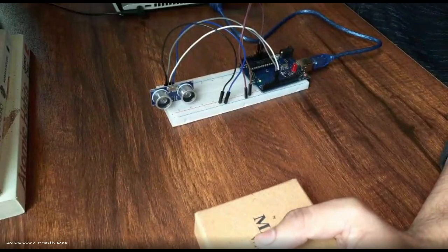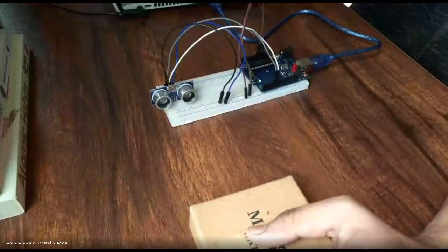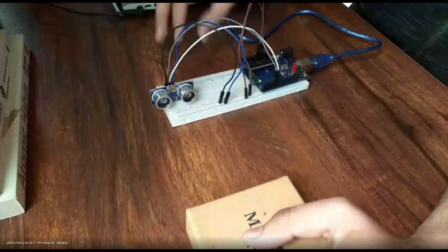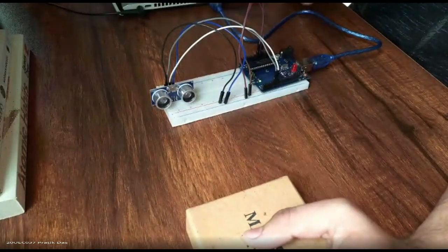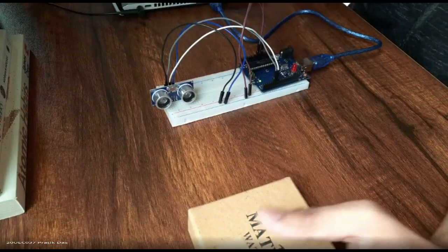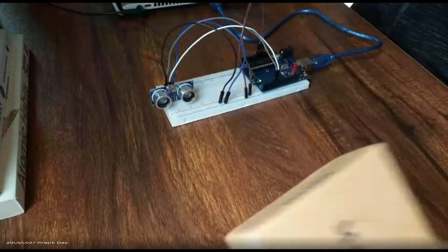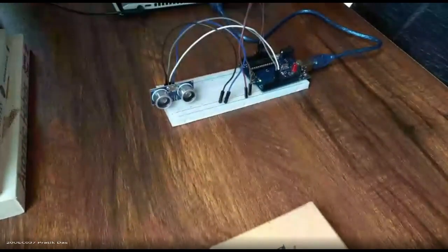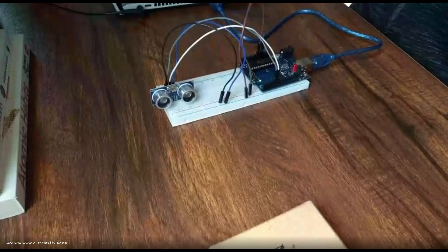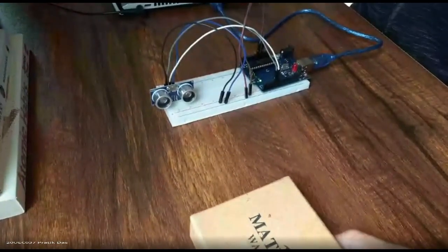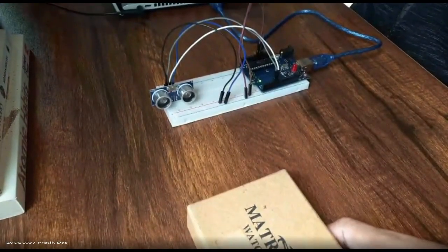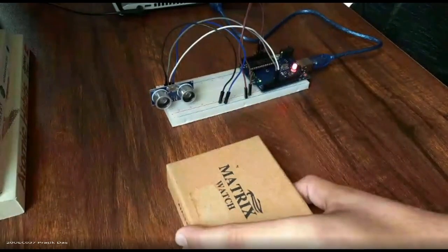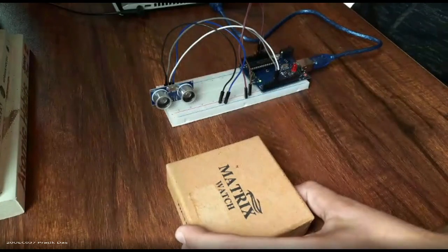So our objective is that if an object comes too close, it alerts us. I've set it so that if an object comes within a range of 10 centimeters, it will show me an alarm. For the alarm, I'm using this LED here. So for example, I am considering this as an object. If it is too far from the ultrasonic sensor, it will not give me any warning. Now if you slowly move it closer, the moment the distance becomes less than 10 centimeters, it should give me a warning. Okay, so let's come closer. You can see we got a warning. The distance is less than 10 centimeters.